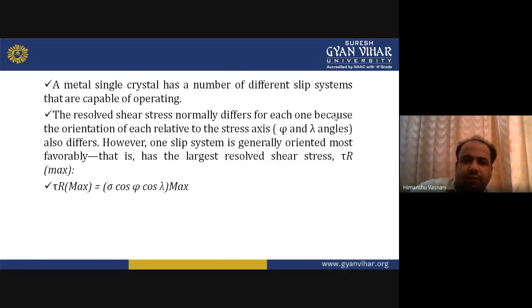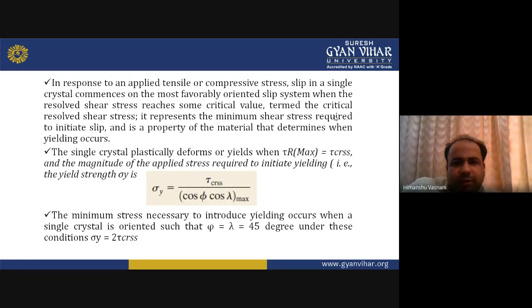Okay, now we'll go further. In response to the applied tensile or compressive stress, slip in a single crystal commences on the most favorably oriented slip system when the resolved shear stress reaches some critical value, termed the critical resolved shear stress.